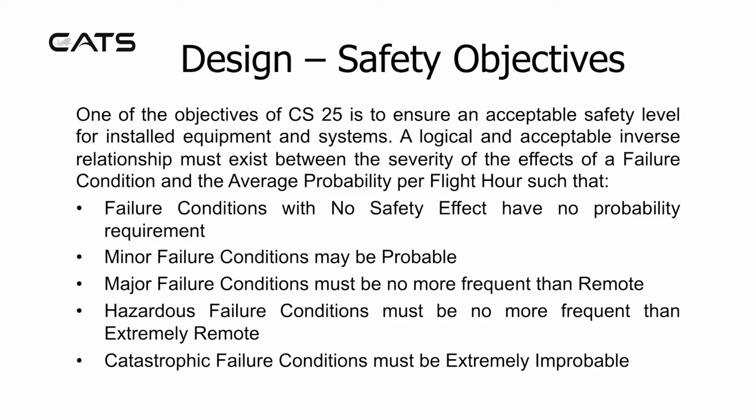Major failure conditions must be no more frequent than remote. Hazardous failure conditions must be no more frequent than extremely remote. And catastrophic failure conditions must be extremely improbable.